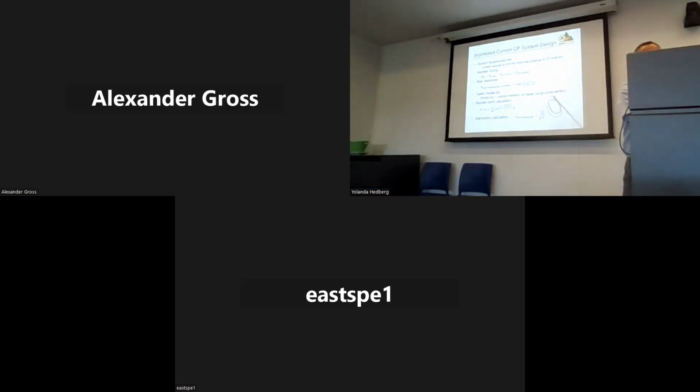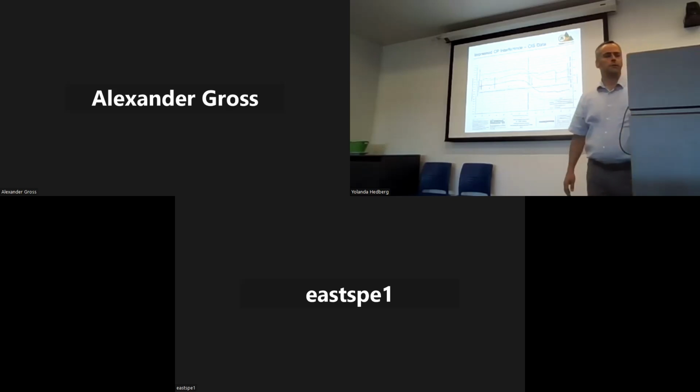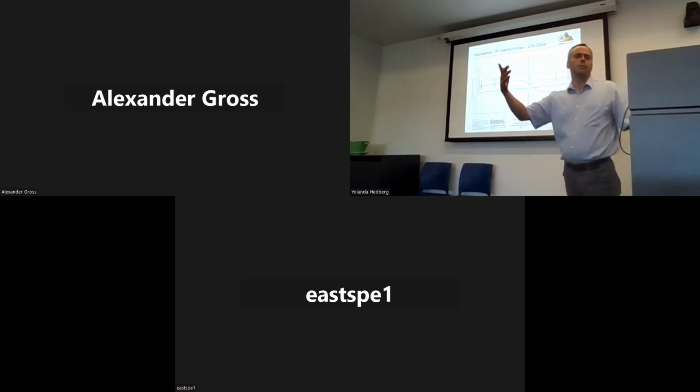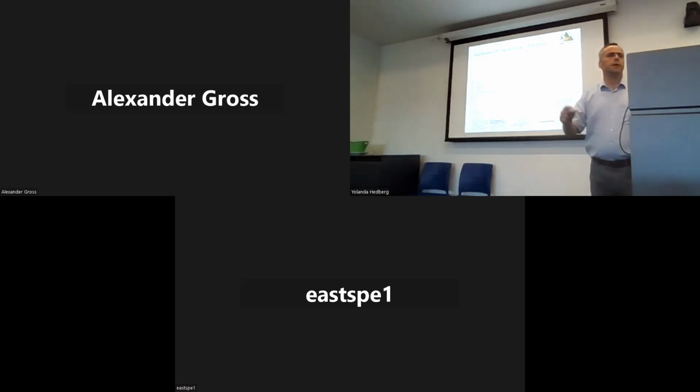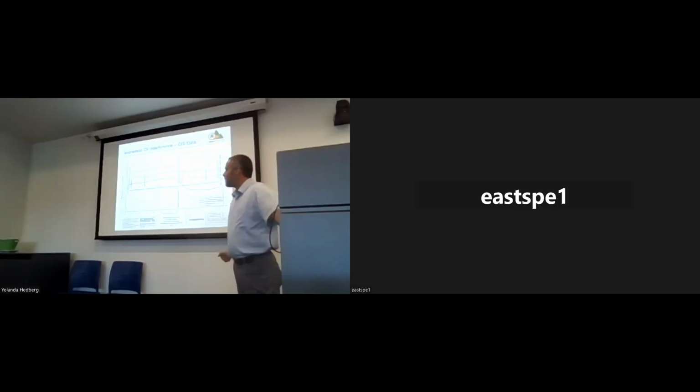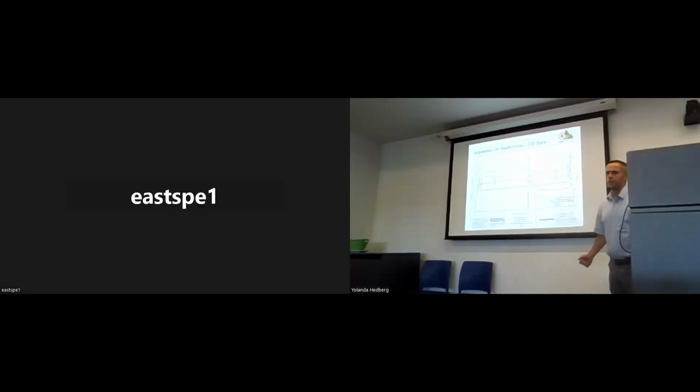I'm going to talk a little bit on an example case study of interference. Ed's seen this slide before, but I'll go into a little more detail. This is some cathodic protection data, and we're trying to achieve the cathodic protection criterion at this site. We're trying to get to our blue line, either negative 850 to copper sulfate or 100 millivolts of polarization.